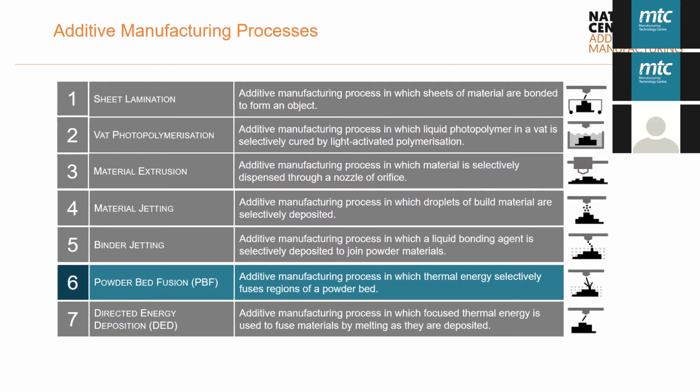Yeah, I think that was in relation to most of the polymer ones that pointed out limitations in mechanical properties. You're right that the layering aspect of additive manufacturing does have an impact on this. So your Z strength, as the part is built in Z, often will be lower than in the XY plane. This is most certainly the case with material extrusion. But that doesn't mean that you can't achieve good mechanical properties. It's just that for the most common materials, you are a bit more limited.